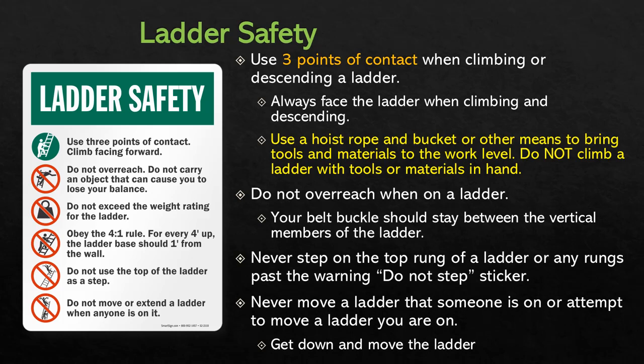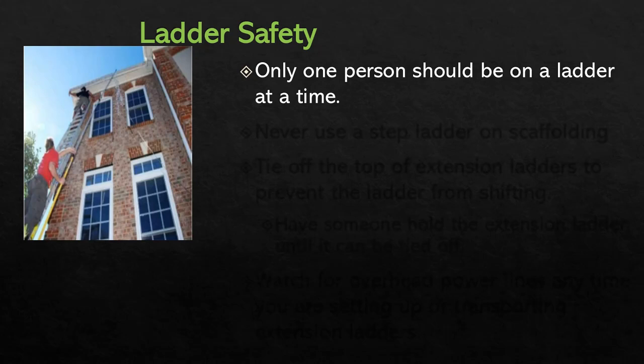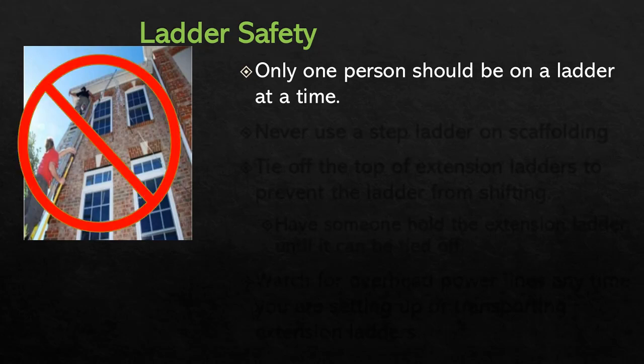This should go without saying, but never move a ladder that someone is on, and never attempt to move a ladder that you are on. You should get down and move the ladder. Unless a ladder is specifically designed for more than one person to be on it at a time, which most ladders are not designed for and are not rated for, under almost all foreseeable circumstances, only one person should be on a ladder at a time.